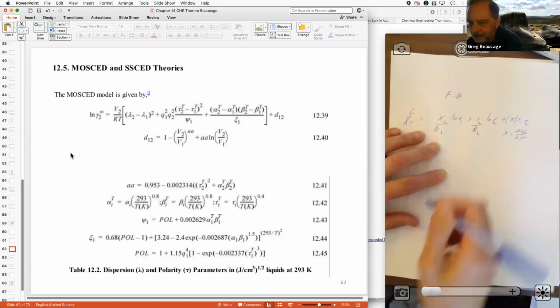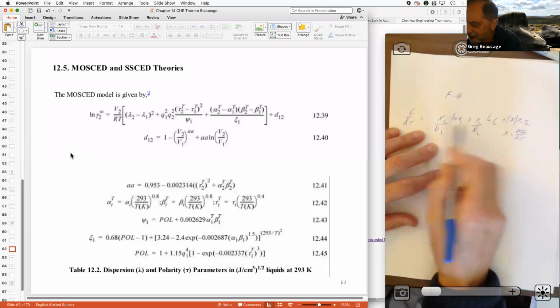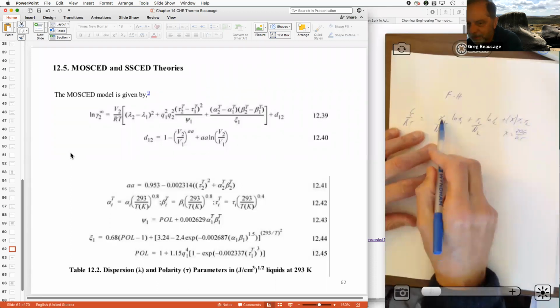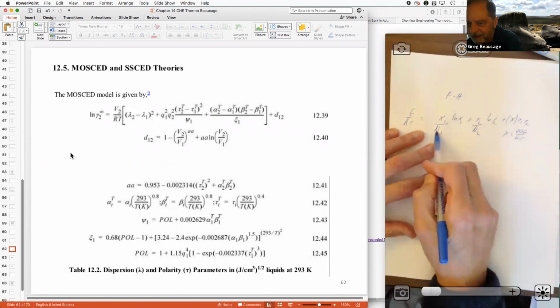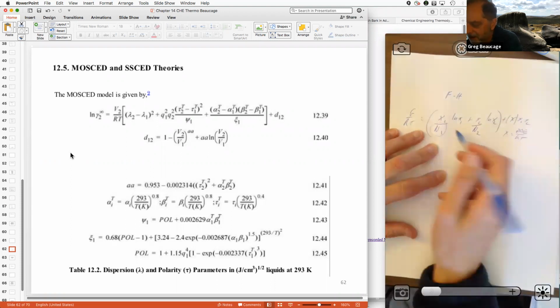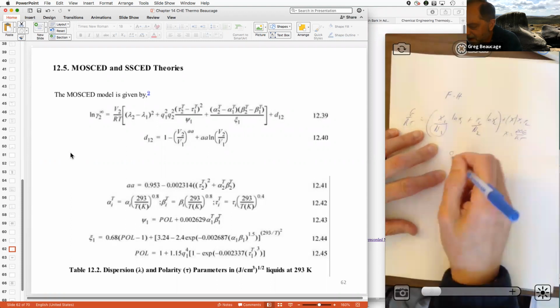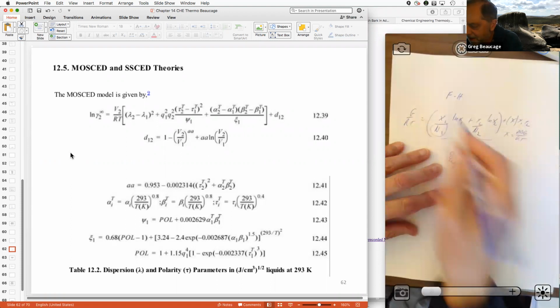So if you have two polymers mixing, the entropy is less because they're glued together. So this is a mole fraction of monomers, and N is the molecular weight, the number of monomers. So the ideal entropy part is reduced because they can't move, they're stuck together in a chain. So that's basically the Flory-Huggins equation, right?